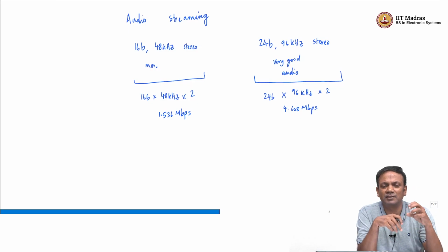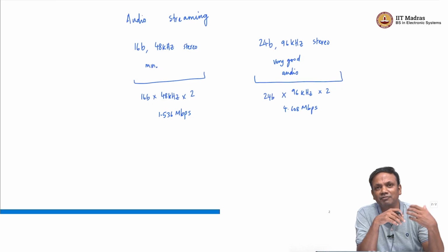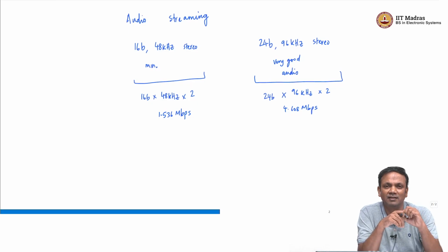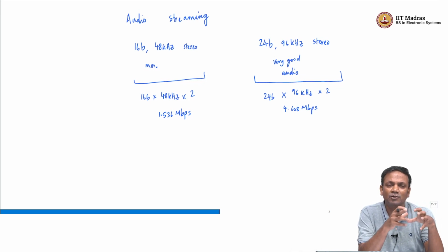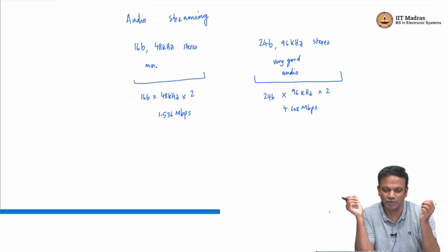Right. So it is important to reduce the amount of information that is going over the channel, so you get as much range as possible. Channel bandwidth is strongly correlated with the amount of range you can get. Higher the channel bandwidth utilization, lower the range you are going to get.